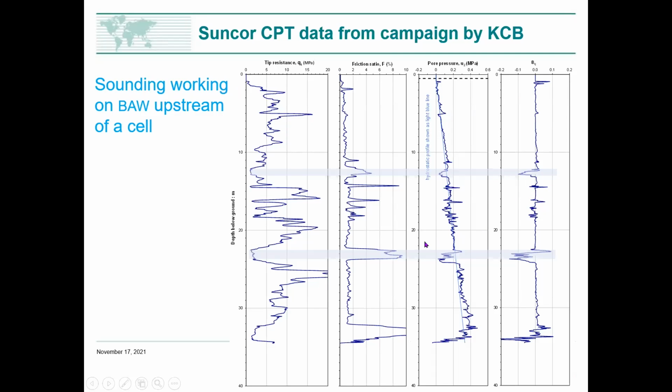And it's basically drained, but you see it's got a couple of glitches. We have put these glitches down to residual bitumen contamination. Curiously, you can see here they get negative excess pore pressures. There was a slight positive kick there, but the contamination seems to bizarrely be slightly dilatant.